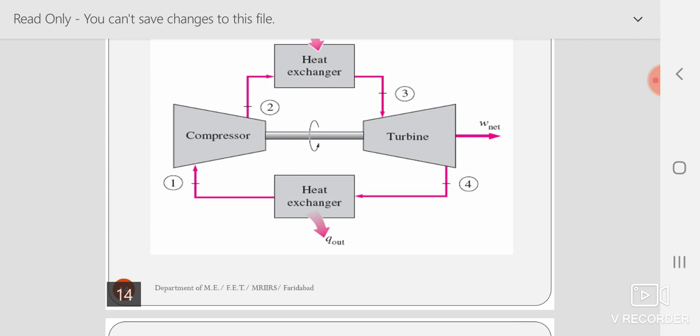There are screw compressors, there are reciprocating compressors, there are centrifugal compressors. You have to compare the compressors. The reciprocating compressor is a very old-fashioned compressor. What happens in a reciprocating compressor? It is a simple piston cylinder arrangement. The piston goes up and compresses the gas inside the piston cylinder arrangement. The frictional horsepower loss is very high in a reciprocating compressor. In case of centrifugal compressor and screw compressor, the frictional horsepower loss is comparatively very less.